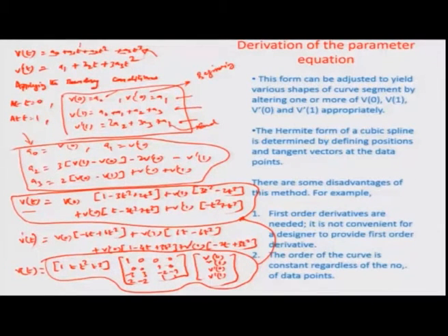So, here computationally what we can do is to actually let off all these different end conditions in terms of the coordinate values and the slopes, and vary the t between limits 0 and 1, or maybe a local t which varies between some value to some value, a t min and a t maximum. Maybe it can be 1/3 and 2/3, or it can be half and 0.67, 2/3, something like that, and be able to plot on a local basis the section of the curve that we would like to have in this particular case.